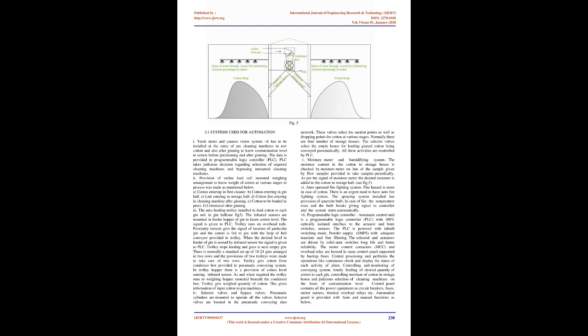2. The cotton seed is fed manually to each gin. Due to irregular feeding, sometimes the gin may run empty. This leads to underutilization of gin capacity. 3. Improper moisture control in cotton due to lack of an auto-controlled moisturizing system. 4. This system doesn't have an online facility for getting information on the quantity of cotton at various stages in the process of ginning, which is useful in judging the efficiency of machineries.